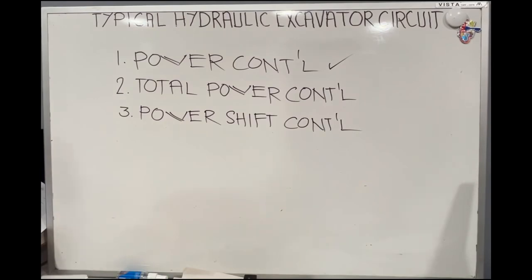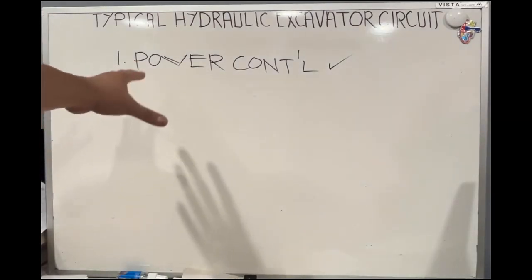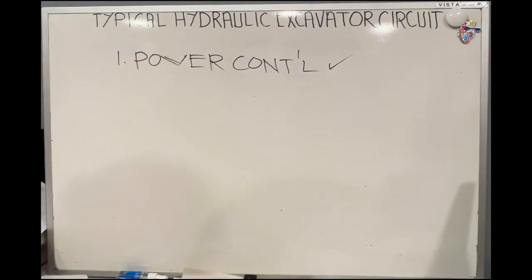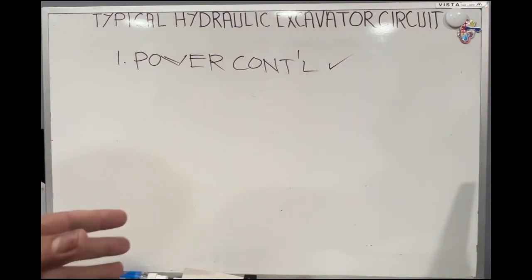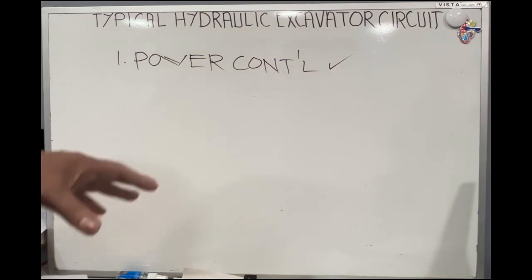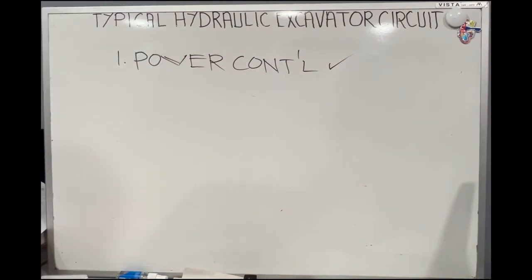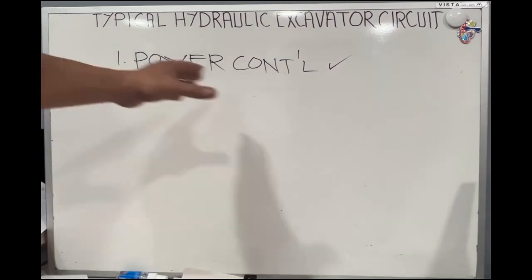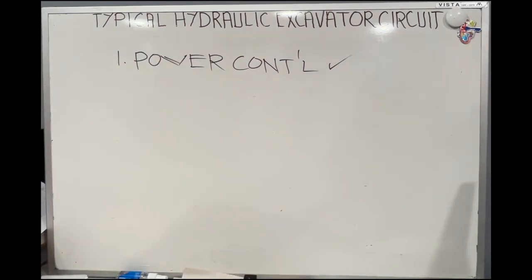Okay, so again, the power control is a function of the load. It's not the direct result of an operator control, but it is a function of the load that is acting on the pump. So that's the power control. By the way, power control is not really the right term. The right term is a torque limit control.